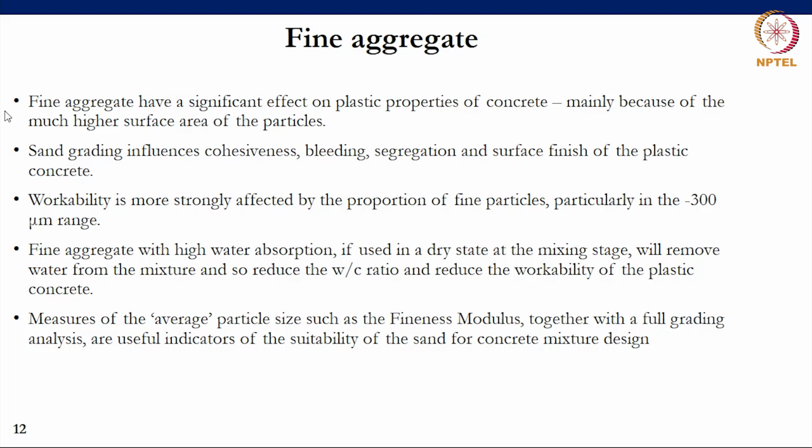Measures of the average particle size, and depending on what the standards refer to, mostly people speak about the fineness modulus of the sand, together with an understanding of the full grading profile of the sand particles, are very useful indicators of the suitability of sand in a concrete mixture. And a mix designer would do well to pay attention and become familiar with the influences of different forms of grading and different fineness properties of aggregates, and particularly sand aggregates. Let's consider some examples now.